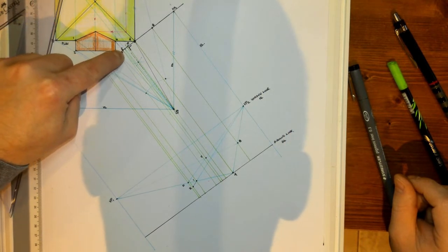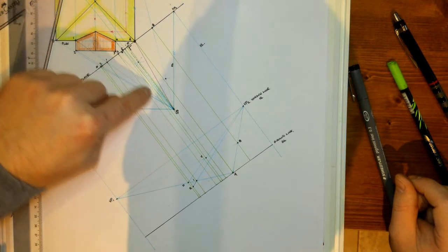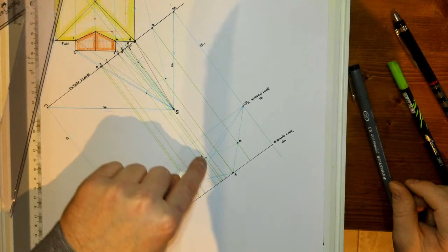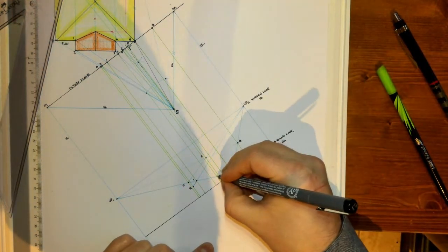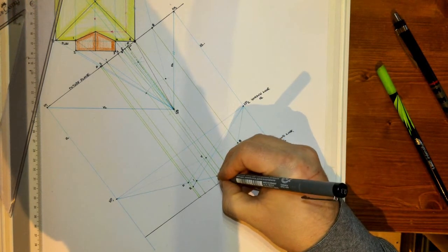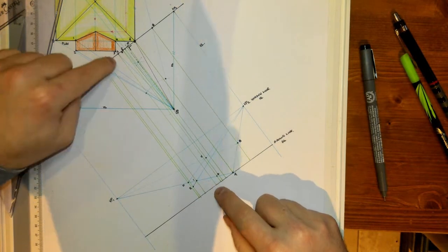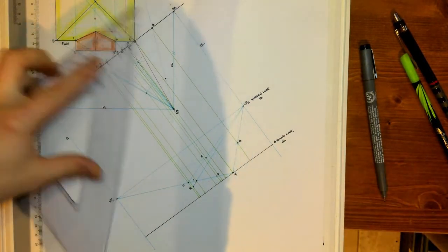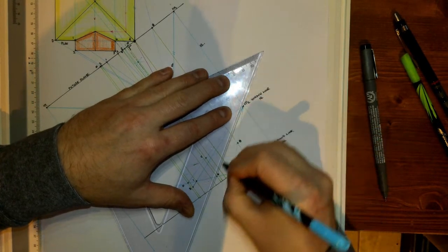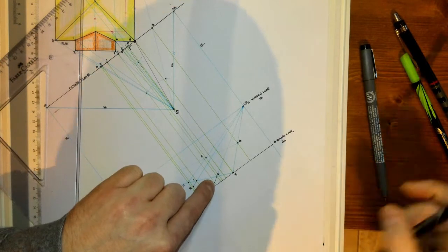Right there. Now, point 4, we'll go there first. So here's point 4, brought back to S, there's where it crosses the picture plane, bring it down, and as I can read it all the way down, point 4 is right here. So we'll mark that point 4. And to find point 3, we'll use the same trick we used the last time. From VP2, we go to point 4 and extend it on out to meet the line coming down from point 3, which is right here.